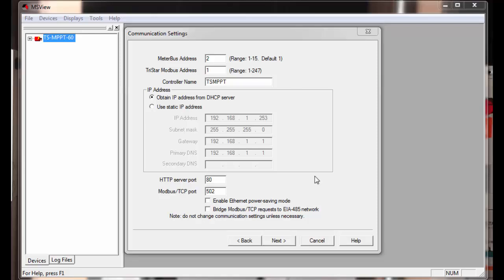Again, these are settings which will not depend on dip switch settings other than the IP settings, dip switch 8, which enables you to program the controller with the Ethernet connection. So in that sense, yes, it will be affected whether you can actually do anything other than monitor using Ethernet.